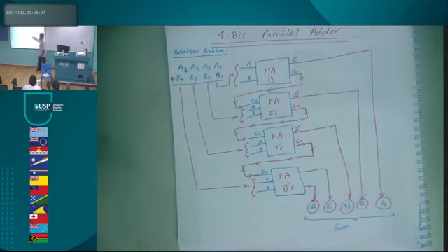The carry out of the second full adder goes into the carry in of the second of the fours, and it continues. All right? Okay. So this is how you build it. And of course, this is called scaling the system. This here is how you scale digital logic.